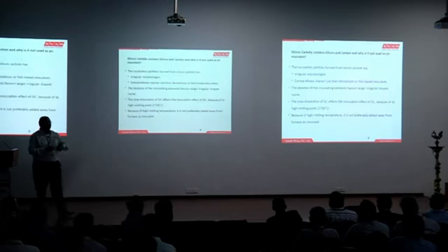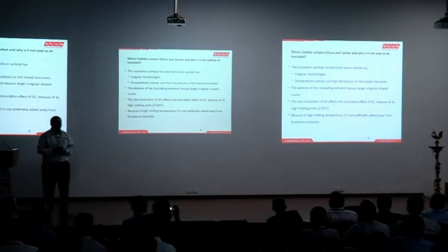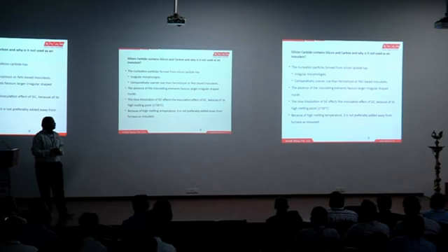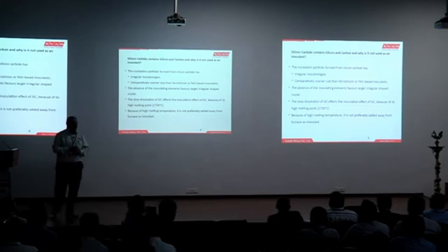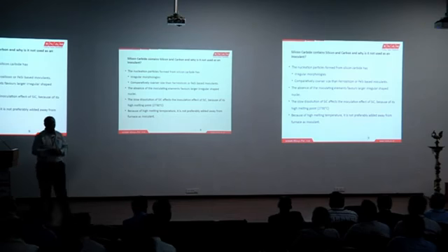There is another compound called silicon carbide, which contains silicon and carbon. Why can it not be used for inoculation? Because of silicon carbide's melting temperature and the impurities present in it, there can be inconsistent dissolution, because of the characteristics of the material as well as the process of the foundry itself.